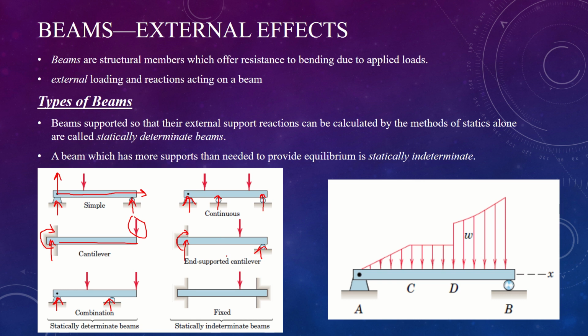Sum of forces acting upward should be equal and opposite to sum of forces acting downwards, and the moment of that force about the fixed end is also going to create an equal and opposite counter moment. So you got 3 unknowns and 2 equations, indeterminate.